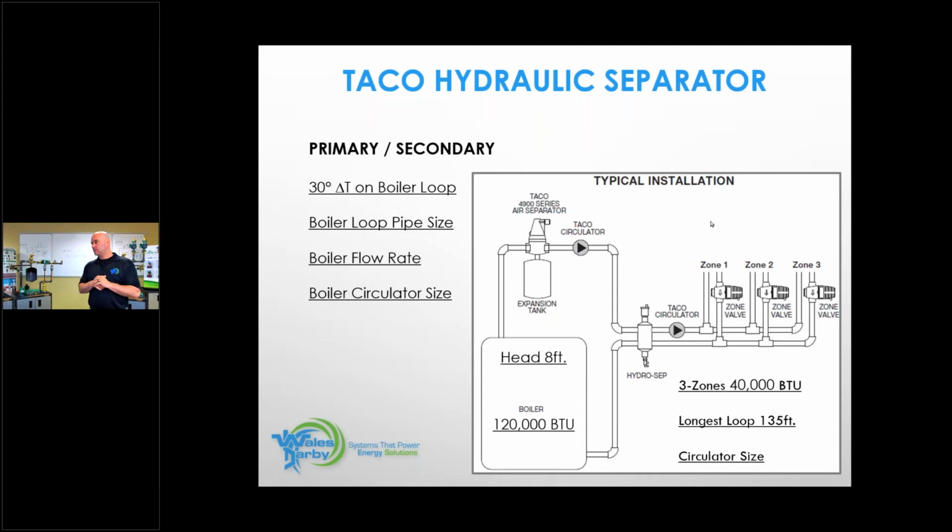A couple answers on the system pump. Yep, 0010. I like a 0010, 0010, 0026E. If anybody gets real adventurous and wants a temperature control, a BT2218 will also work on that side. So there's the circulators. We'll just walk through this. I always say do what you know first. 30-degree delta, go back to that universal hydronic formula, calculate it out. Every gallon of water has the ability to absorb and deliver 15,000 BTU.